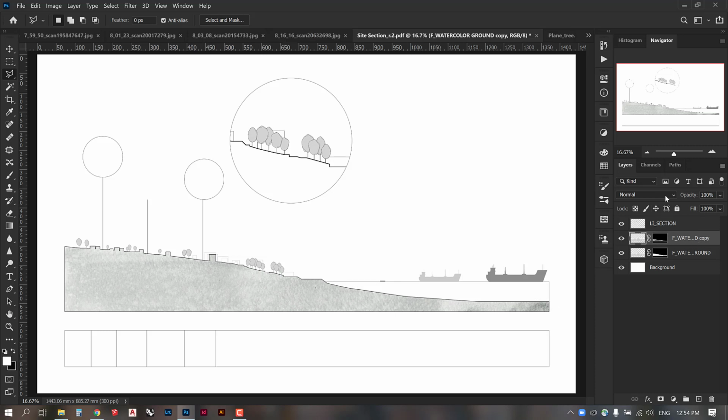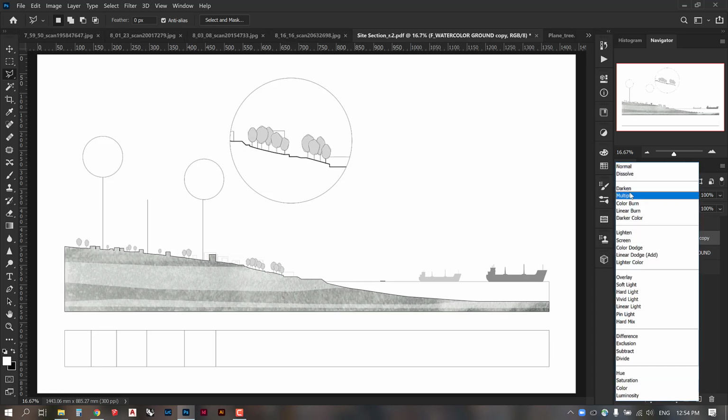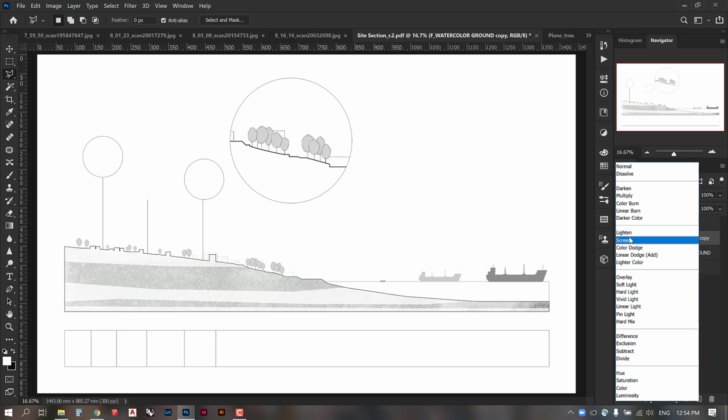Now I'm going to use a blend mode to make this show up differently. So if I go to multiply, you can see that the portions of the texture that are left over are now being added in a new way and blended with the layer beneath them. So multiply is one thing you could use. If you just hover over all of these different blend modes, you can see what impact they have on the texture below.